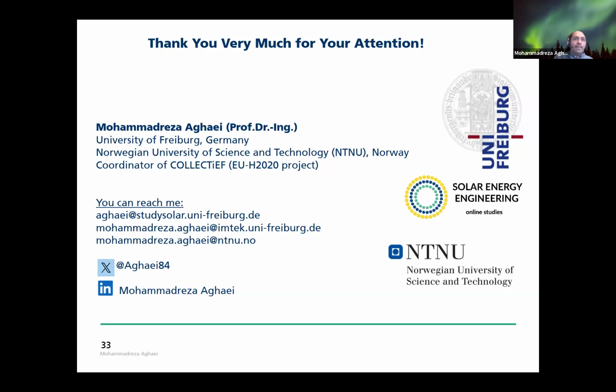we are able to map the plant, and then based on the aerial inspection using, for instance, RoboPV or similar products, you are able to detect it in real time. So you know when and exactly which string, which panel, and even which part of the panel is affected by the failures. There are several methods, but normally in the novel methods, like autonomous monitoring, everything will be real time or semi-real time. So you know where you can find the failures and do the remedial action for it.